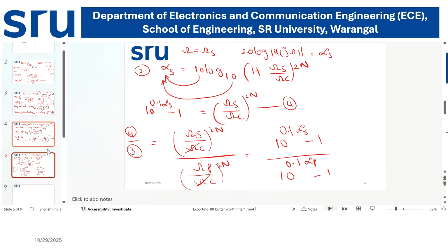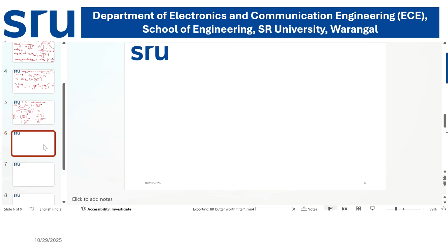Now we have (omega s by omega p) whole power 2n is equal to 10 power 0.1 alpha s minus 1 by 10 power 0.1 alpha p minus 1.